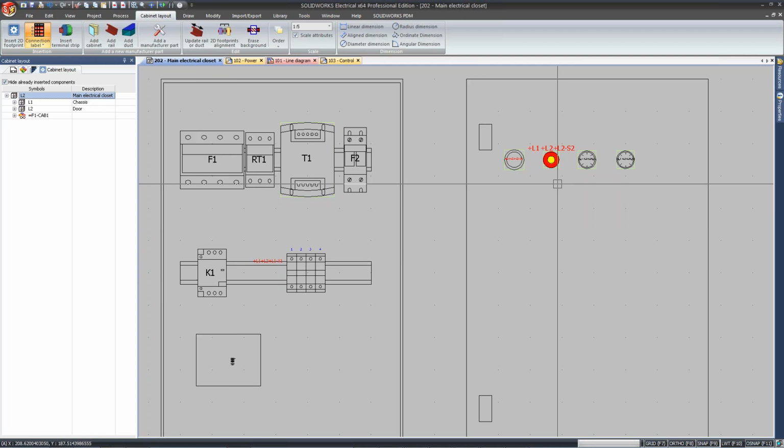And if I'm connecting twice, it means that I'm going from this area to the other area, the chassis, from the door to the chassis twice. So that means that I'm spending a lot of wire length here. It would be better to just connect from here to here once, and then internally connect all these components together. That would save me some money, some wire length.